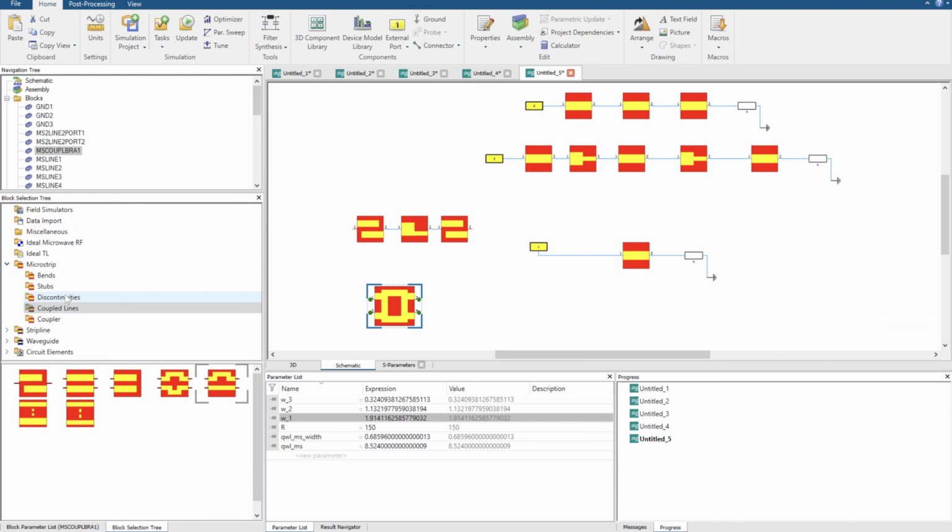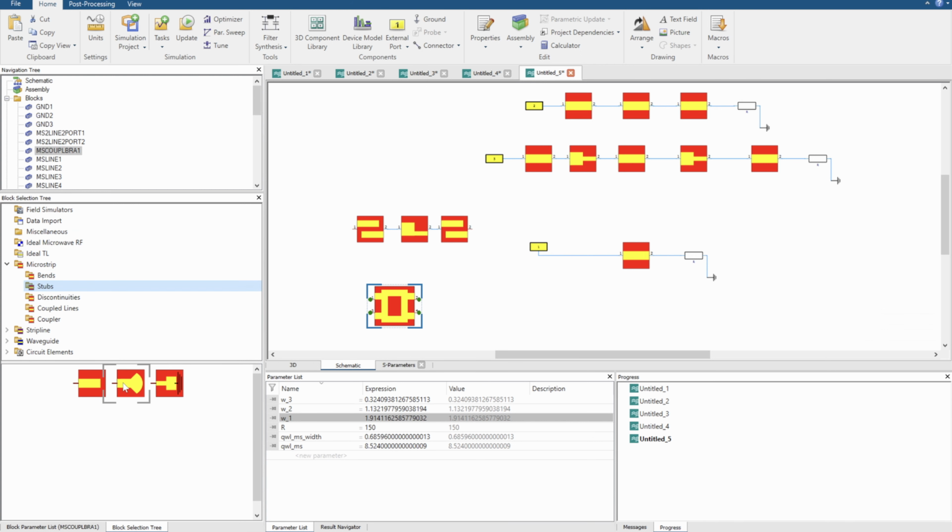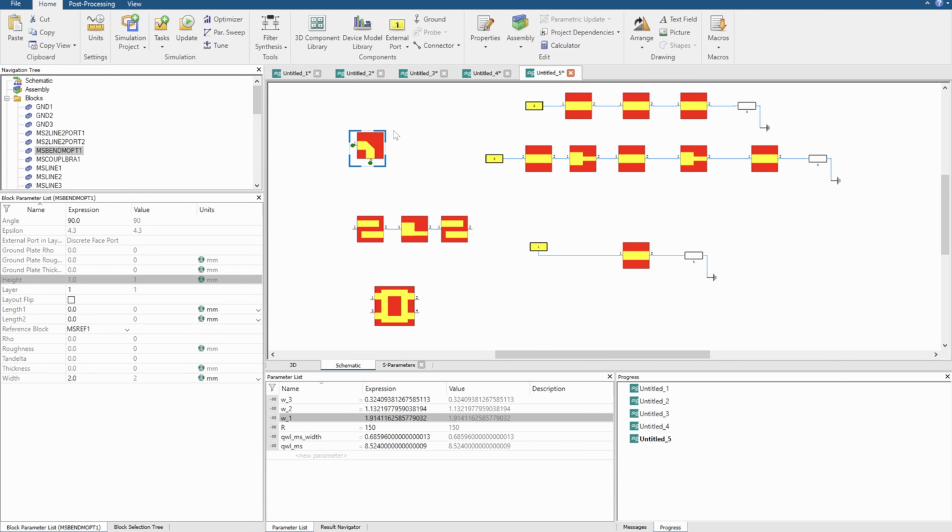Okay, so please do go ahead and try stuff. You know, we've got radial stubs, we've got all different types of bends. Remember, if you do expect a bend to be in your final design, always account for it in the schematic tool, because your goal in the schematic tool is to do quick, very fast prototyping and optimization of full circuits that you then expect to transform into 3D. However, you don't want to do it straight away into 3D because you want to fine tune values, and you don't have 6 years to do evolution strategy in 3D, which doesn't seem viable without a supercomputer.